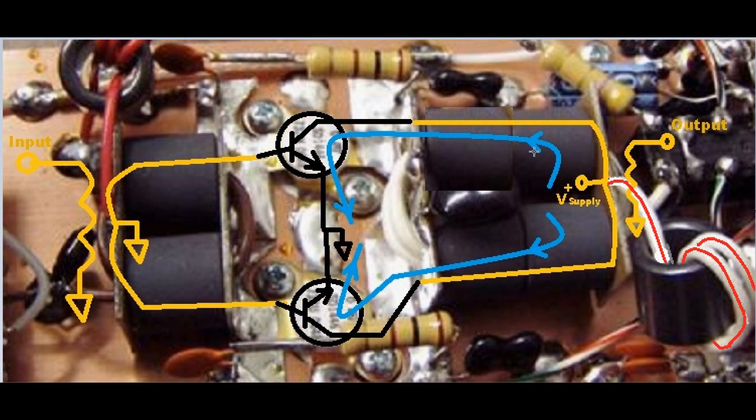The copper tubes going through underneath these ferrites represent the load. It's a single turn center tapped, which is our center tapped winding on the load side. And then this white wire here, which you can also see over here, wrapping through the air gap on the output transformer, represents our secondary winding. It's single-ended, which is our output, shown here in the circuit diagram.